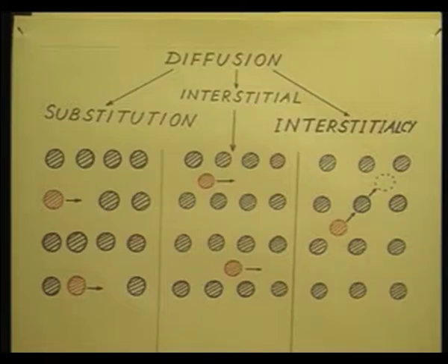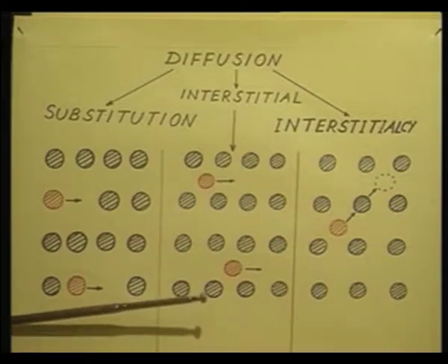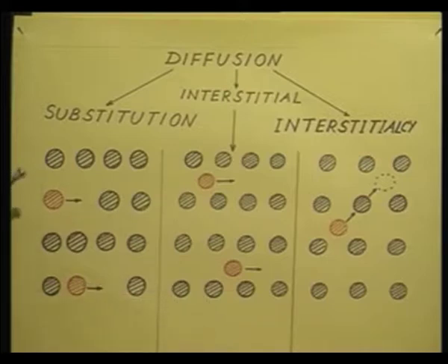So, let us assume that this is the direction of the bulk, that is, on the left of the figure I have the surface. So, at the surface I have a high concentration gradient. I can see a dopant atom sitting here, and next to the dopant atom I have shown a vacant site.